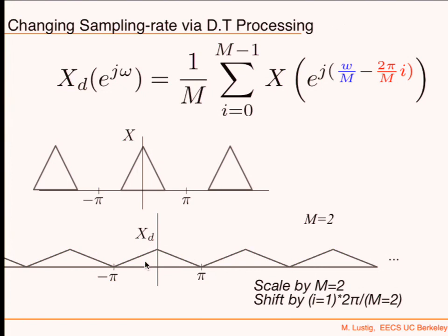It kind of makes sense, because if I had sampled a signal that was band limited at half the rate, so if I sample it at a certain rate and I've got a bandwidth of π/2 left on both sides, if I had sampled it at half the rate, I wouldn't get aliasing, and it would cover −π to π. Take a look at this.